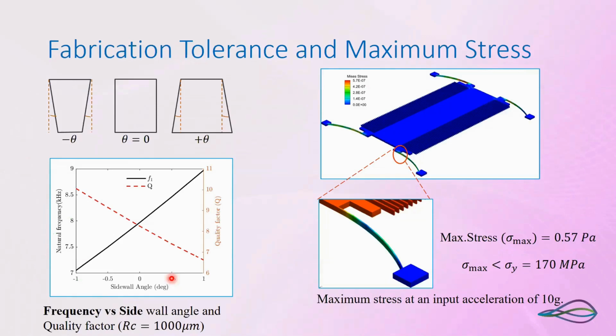And when you take the thick beam, whenever you go to the DRIE process, there is a possibility of getting the thickness inclined. So it doesn't remain the same, but inclines. Because of this inclination, we have a fabrication defect. So when we design, those things also need to be taken care of. So here that wall variation is being changed from, you can see, -1 to 1,